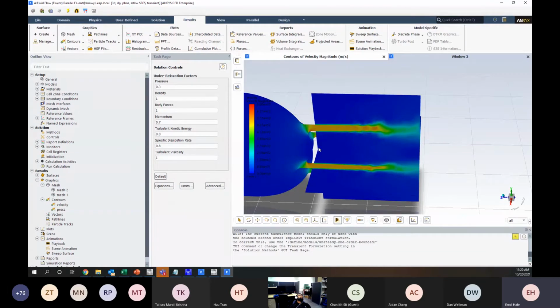Also, the mesh independent study is more of a comparison between multiple simulations rather than a comparison between simulation and real life. So my mesh independent study for this might be trying to get maybe your standard deviation at the outlet and changing your mesh densities until that outlet quantity stops changing.